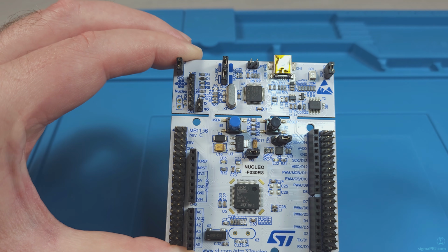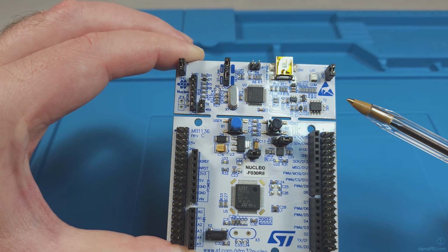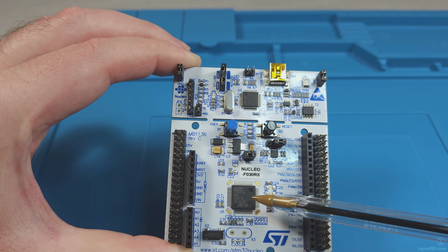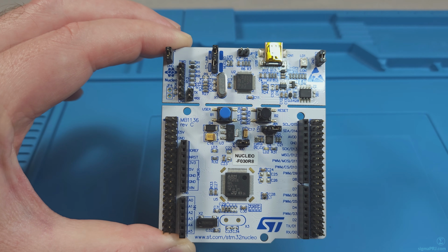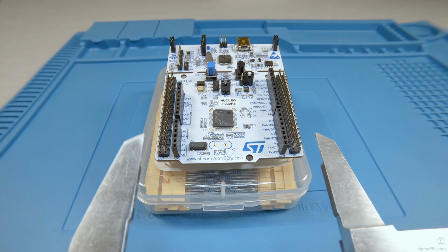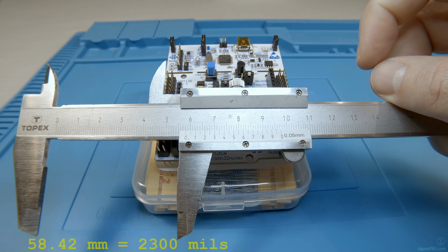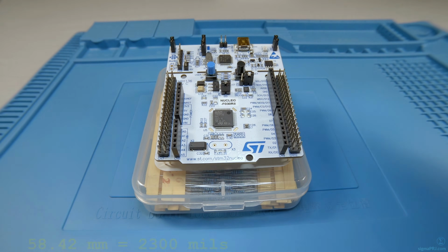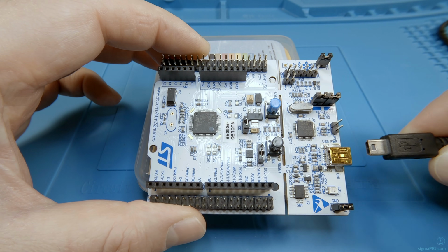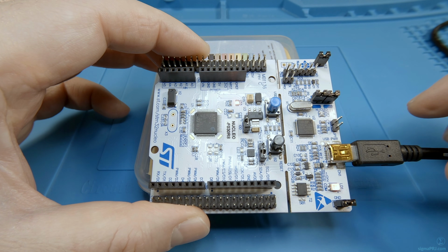We can notice here that this board consists of 2 parts. The top one is responsible to establish SWD debugging protocol with your PC, while the bottom one has our target STM chip itself and few peripherals. During our PCB layout design, we have to know exact distance between connector pins. So this development board has exact number of 2300 mils between them. In order to use this board for debugging purposes, we just have to plug it to PC using this USB connector, and this will be automatically recognized by STM CubeIDE.